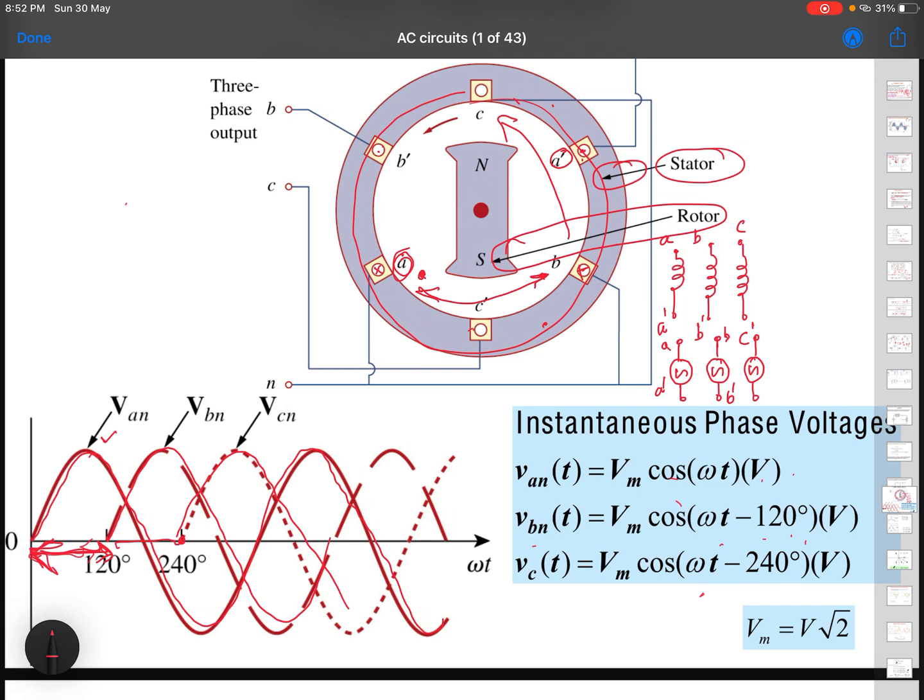The second thing is, when you place these coils in this way, it also gives the prime mover a constant amount of torque. When you are rotating it, at times when there is EMF generated or current flowing, you see more opposing torque on this electromagnet. And when there is no EMF produced, no opposing torque would be there.